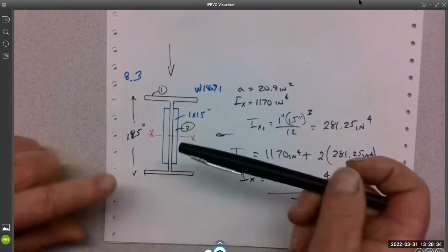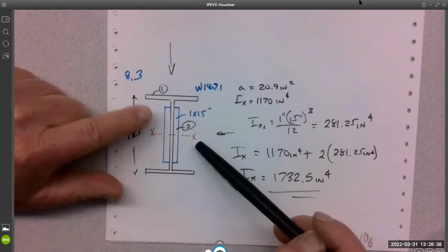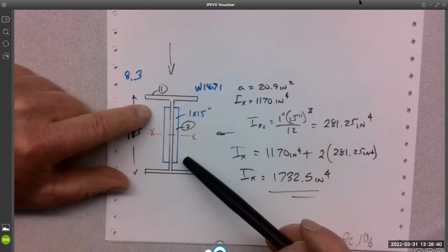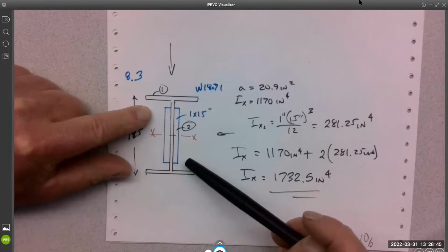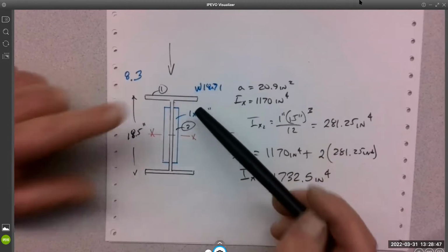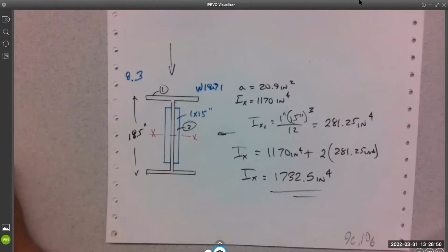When I've done this, designing trailers, they really wanted us to use available steel that we had in the yard, and we had a pretty big yard of steel. I would find something, go do the calculations. It would be just short of what I needed, and I'd just find some plate steel and say, let's just weld this onto the web, and we'll have enough and go. So you see it like that, and then you also see it in reinforcement in areas of excessive bending stress.